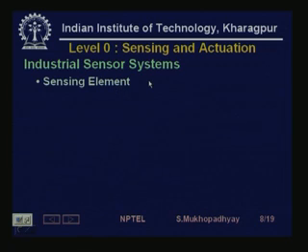So, when I say a sensing element comes along with all its packaging, this packaging can have some effect on the control performance of the loops, because they have their own dynamics. Thermo wells introduce time constants into thermocouples, as we will see. So we have a sensing element.